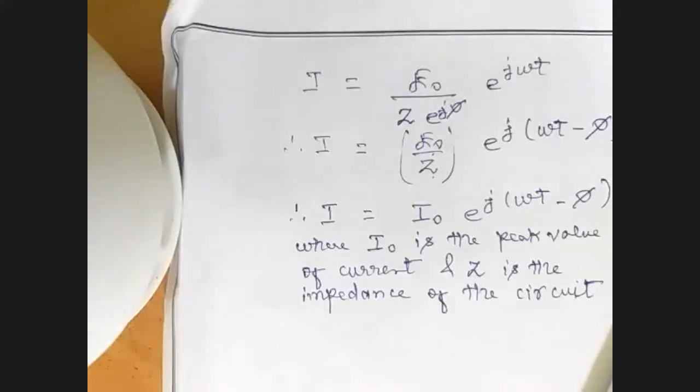And let's check out the play between the values of phi. So now equation 3 can be concluded with respect to the values of phi. One thing is sure from equation number 3, that current has a certain phase difference with voltage. But whether it is leading or lagging depends on the value of phi, where phi can be positive, negative or zero also.